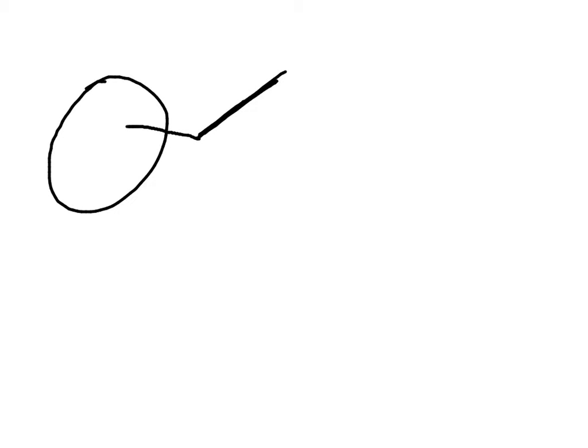If you look at slide 27, you've got a tyre, and if this is my tyre, use your imagination if you can't quite see it, but you've got your tool there removing the bolt. As you apply a force here, the force isn't acting just about this point, but it's acting all the way along this axis, that turning effect. So what we can now do is start scaling up. Rather than talking about moments about a point, we're now looking at moments about an axis.